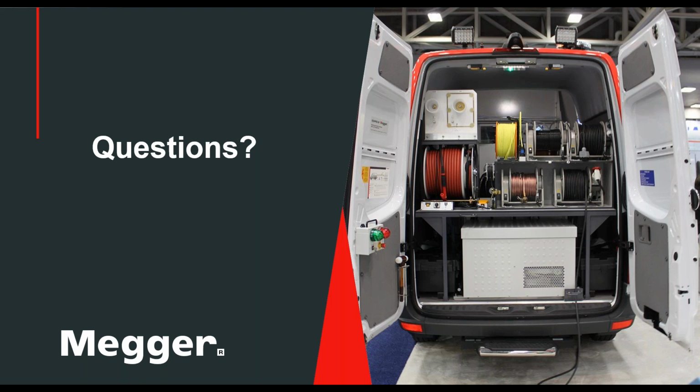Whether it's PILC cable or any other cable, the general rule is, once we've done that breakdown test, we want to use the lowest voltage range available to us. That will provide the largest amount of capacitance, and that's going to give us the largest joule number.